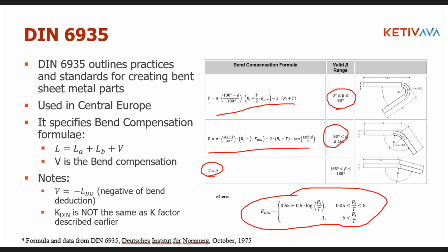And so one of the things when I was working on the Inventor sheet metal, one of the big items that always came from Central Europe is we've got to be able to handle this, because before my tenure on sheet metal, we could only do K factors or bend deduction tables, and neither of those really worked for this formula. So this is why we have formulas in there. This is a really complicated version of it, but you can use these formulas to do things like a simple K factor. So if I'm between this and this, use one K factor. If I'm between this and this in terms of bend angle, use another. Okay?